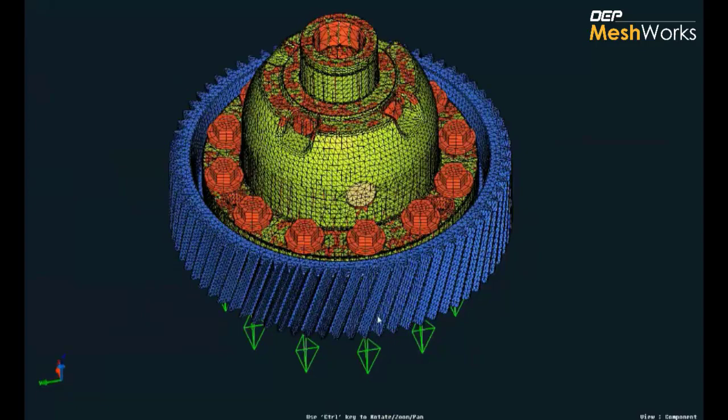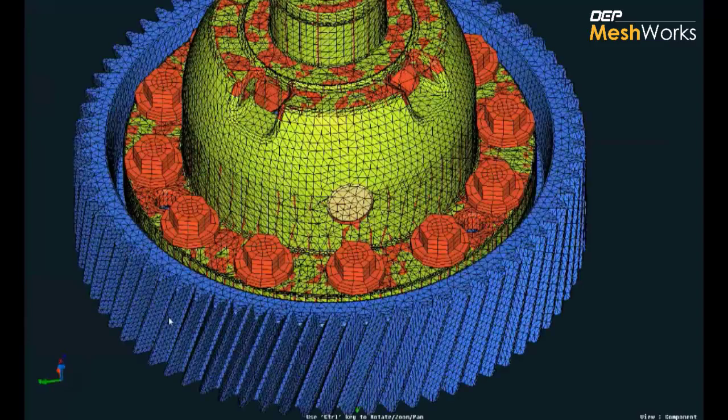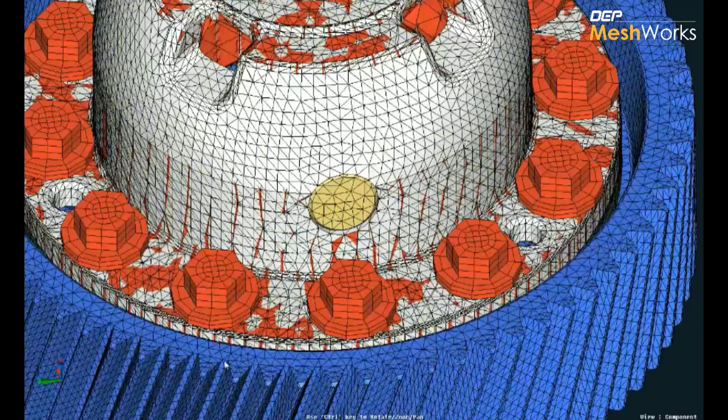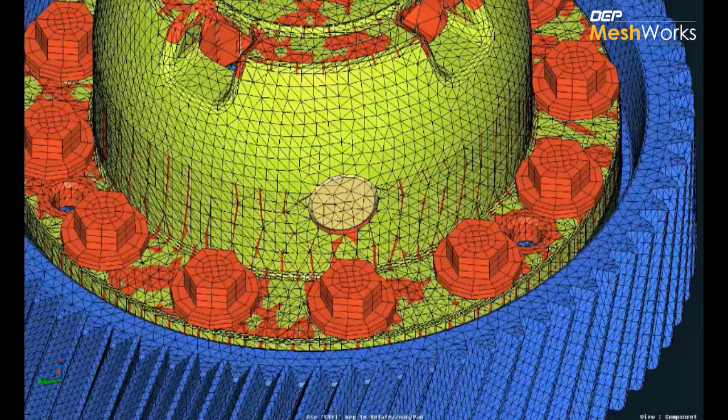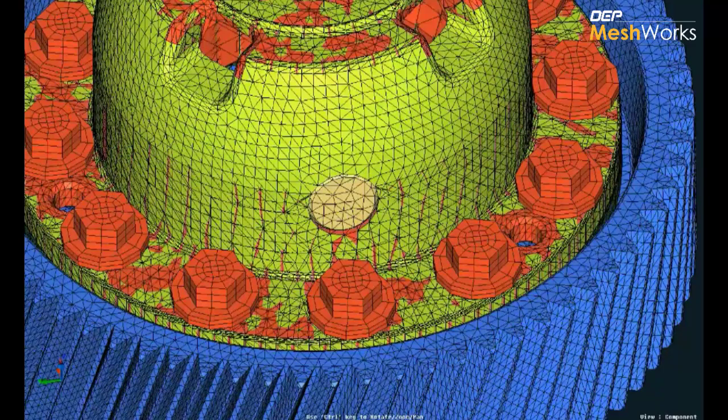So I'm only going to use a meshing attribute file. Here I'm going to choose my current part as the model with the fine mesh, and then the new part as a model with the coarser mesh. In this case it's an FE part and there is no mesh template required, so I'll just say accept.